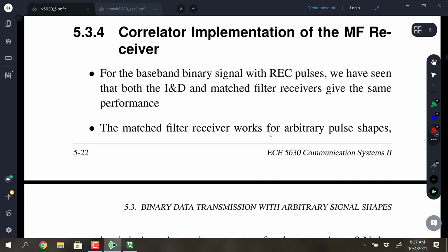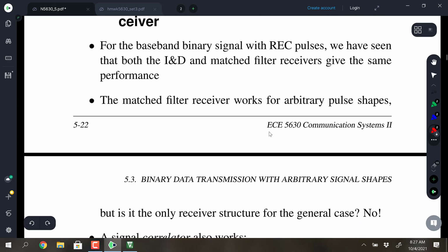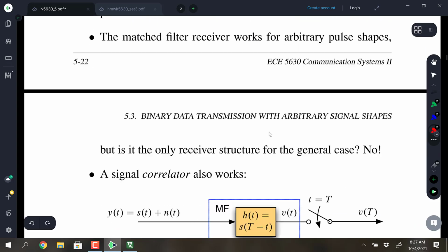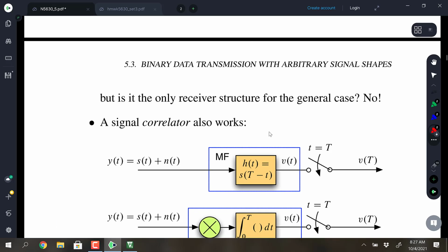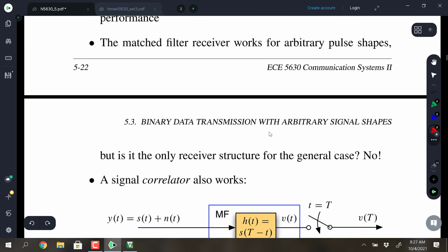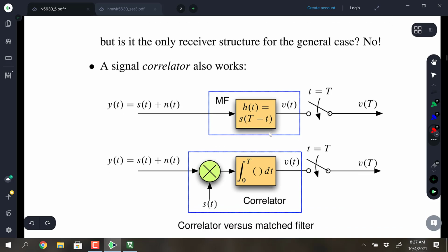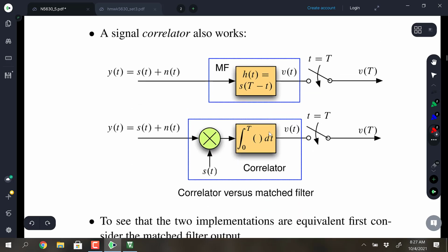It's just integrating up until T seconds, and then you make your decision. That's like the leading edge of the integrating operation of the convolution in the matched filter, and that's like a correlator operation too.